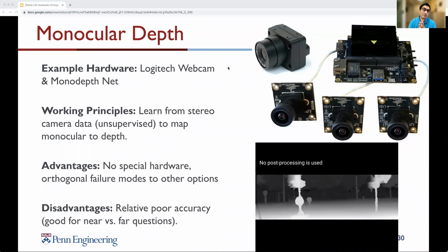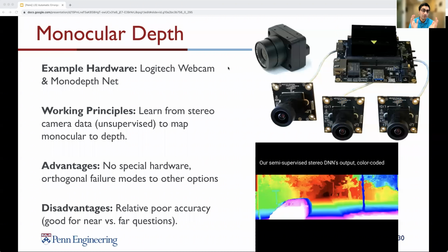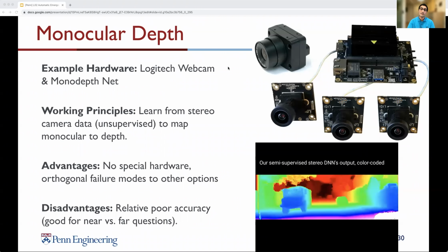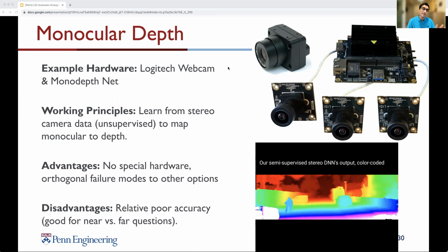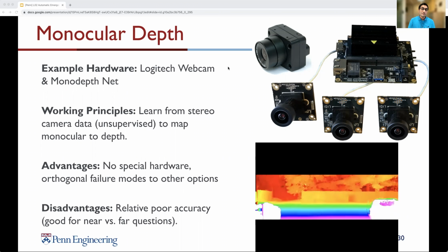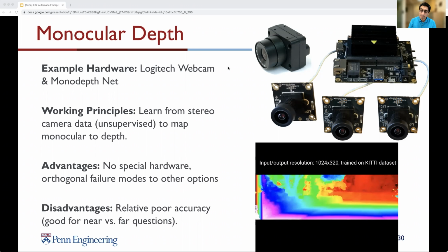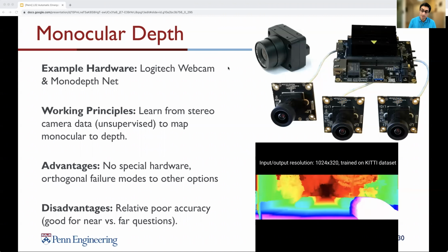The best case error, unfortunately, in this is about 11%. So for an object that's 80 meters away, there's an error of about plus minus 4 meters. And so this is good for many applications such as overtaking on an F1TENTH, but it's not sufficient for safety critical real world driving like that, right? So on the F1TENTH, the cars are kind of meant to crash because that's what we experiment with. So in the bottom right, you can see monodepth in action, and you can see it's actually really impressive. In the past 3-4 years, actually, monocular depth perception has advanced significantly.